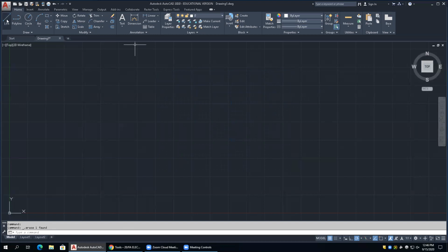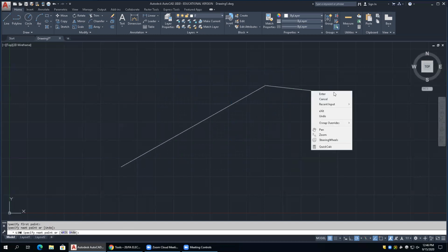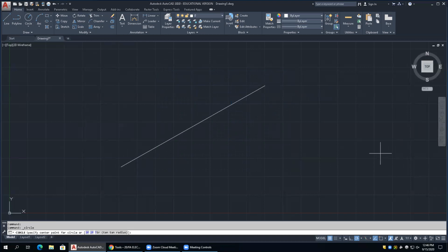All right, so we're gonna kill that. Gonna draw a line here. And I'm gonna draw a circle. All right. So the next one we're gonna take a look at is called break. A break is definitely just a trim, okay? So with break, what you do is you pick 2 points. Like you say, pick a point here and pick a point there, and it's gonna break from the first point to the second point. You don't have a secondary object there, it's just picking 2 points.